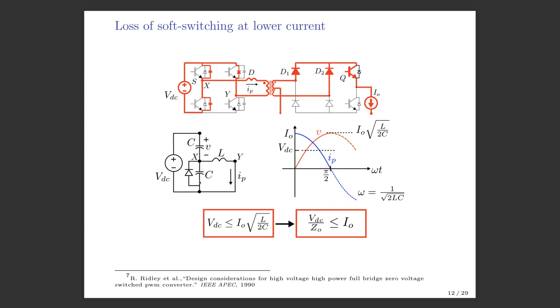So now you have these two capacitors and this leakage inductance of the transformer, that is L, and these two capacitors are those two capacitors that we have added to get soft switching. And this is the pole X, right? And now this diode is not conducting because across it the voltage is VDC, so this diode is reverse biased. So that means now you see that you have got yourself an LC tank circuit, right?